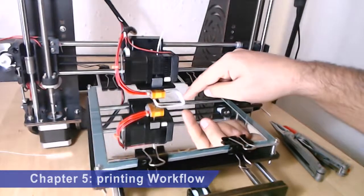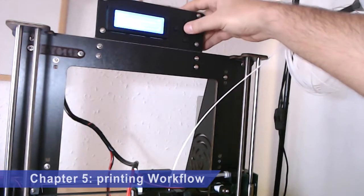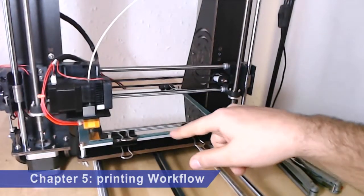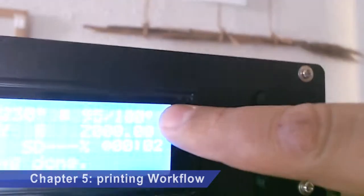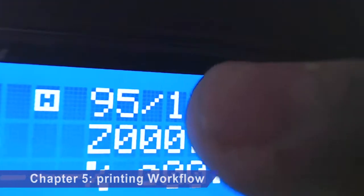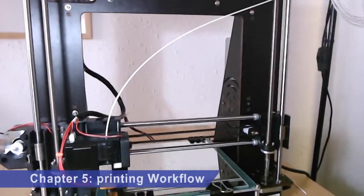Maybe now the base is not sticking so well to the surface, so I'm going to hit stop print. I'm going to prepare and I go to auto home. You know, here the mirror has no temperature control, so maybe you have to wait till the bed parameter in here reaches 100, and when this reaches 100, that is 95 degrees, we wait a little bit more because the mirror in here should also be heated. So we wait a few minutes and we start again.